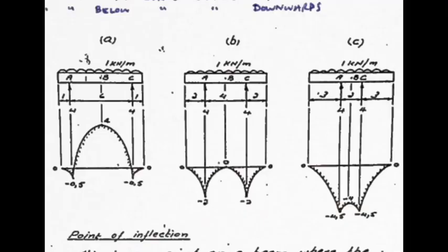And let's use the same beam with 1 kilonewton per meter UDL along its full length, but let's shift the support reactions to 1 meter from the ends, 2 meters from the ends, and 3 meters from the ends. And you can follow the exact same process as before and draw our various bending moment diagrams. And you're going to find the shapes that result here. I want you to try those yourself.